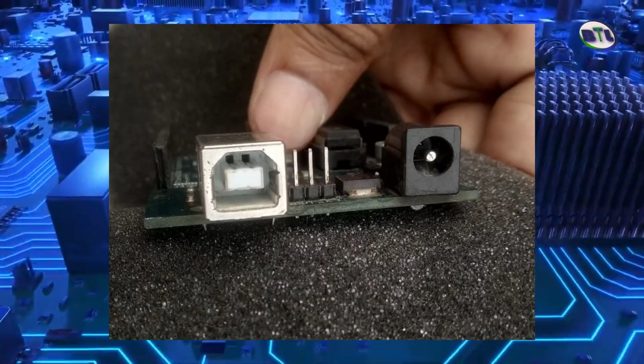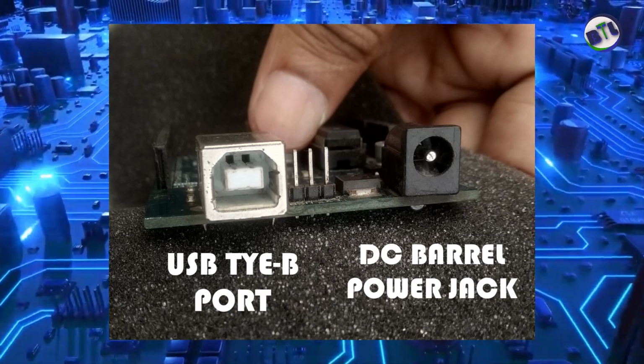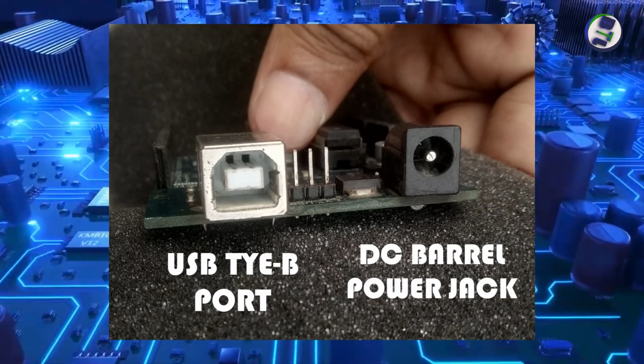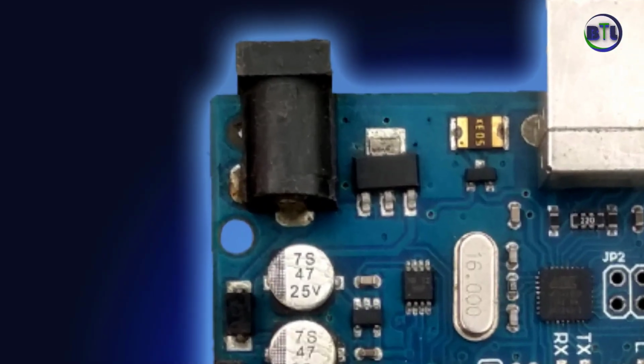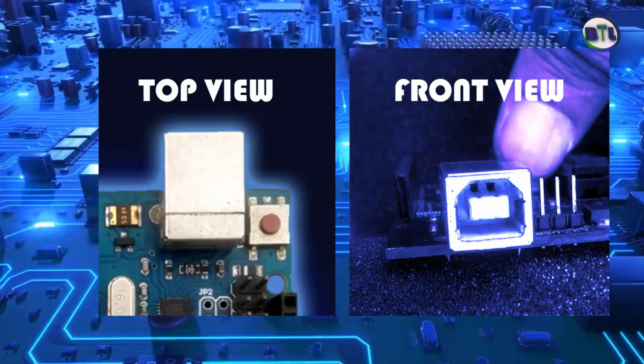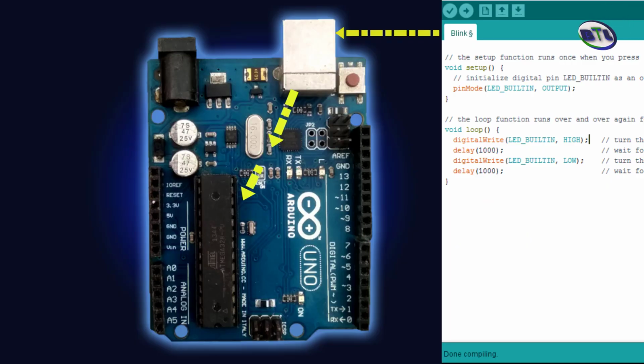Powering up Arduino can be done through the USB cable or via the DC 9V barrel jack separately. It can accept voltages between 7 to 12 volts. The built-in voltage regulator reduces the voltage to 5 volts. The USB port is used for powering our Arduino UNO, uploading our sketches to the microcontroller, and for communicating with your Arduino sketch as well.